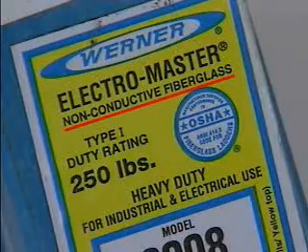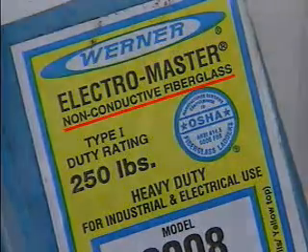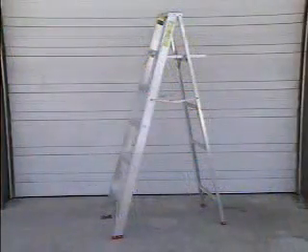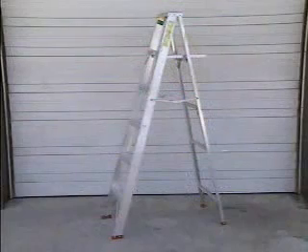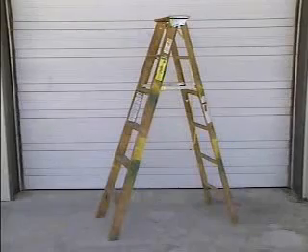The material that the ladder is made of must also be taken into consideration when a ladder is selected. For example, metal ladders aren't suitable for jobs near electrical lines. Fiberglass or wood ladders are a better choice, since fiberglass and dry wood won't conduct electricity. Once a suitable ladder has been selected, it can be inspected and put to use.